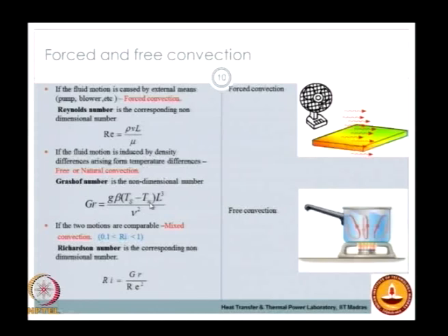In the case of the Reynolds number we use the definition of inertial force to the viscous force. So here the inertia is being replaced by the strength of the buoyancy force, which is related to the temperature difference between the hot side and the cold side. Typically you can look at free convection when you boil a liquid. You do not boil it too much, just during the initial stages of boiling, when you apply lower heat fluxes, you can find these convection currents rising from the heated surface at the bottom upwards towards the cold surface outside. These are small currents which are being set up and which can improve the heat transport.